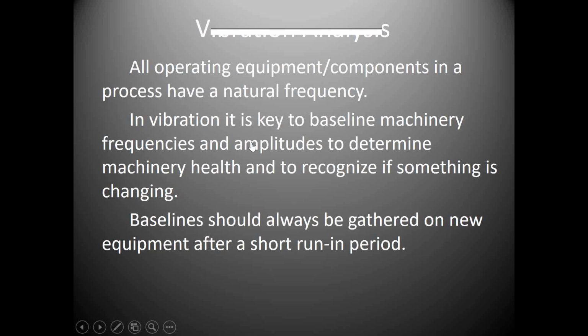But it's key in your equipment with vibration analysis to get some baseline frequencies, especially when the equipment's new or rebuilt. And then you monitor that over time. So some people will say, well, I don't want to do vibration analysis because I don't have any baseline. Well, your baseline is probably going to be the very first test you run. I don't care whether the equipment's a month old or 5 years old. You're developing a baseline as soon as you put the tool on there. But this tool sometimes right away tells you what's going on with that equipment.